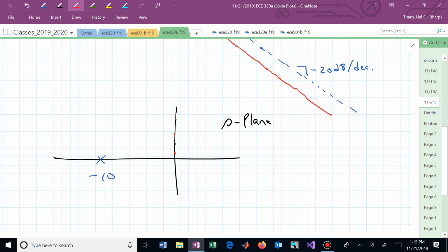If we walked up that axis to j1, what we are agreeing to now in this straight line approximation is, oh, that angle, forget it. It's 0. Any frequencies before that, we're just going to say its angular contribution is 0 because it's small.